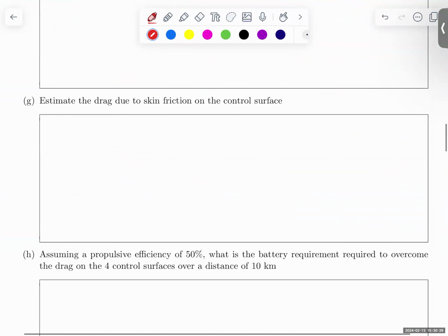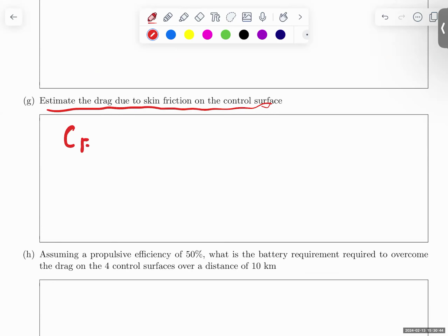Now we'll get to an actual engineering computation. What's the drag on this thing due to skin friction? This goes to that last slide I put in the lecture notes, that kind of how-to map. Now we're dealing with Blasius's third formula, which is the drag coefficient due to skin friction, 1.328, same functional dependence, square root of Reynolds number based on L, the plate length.